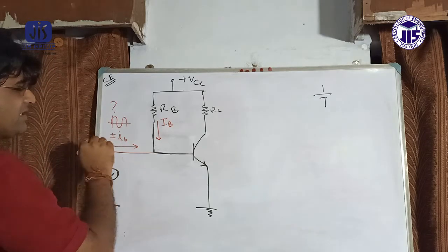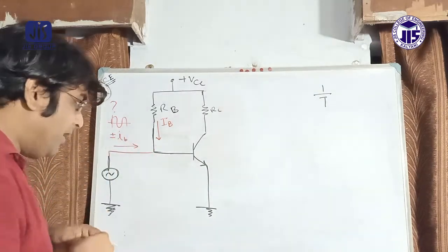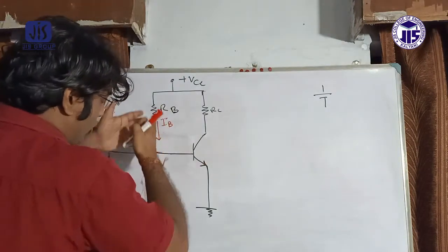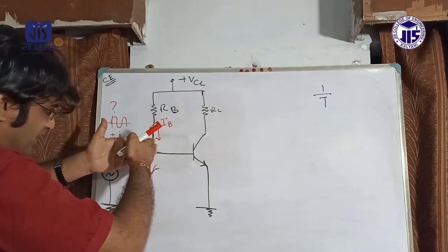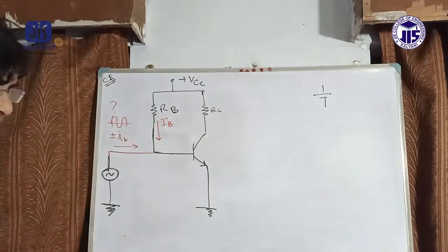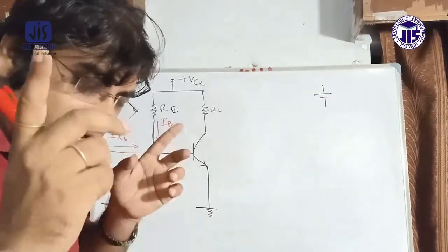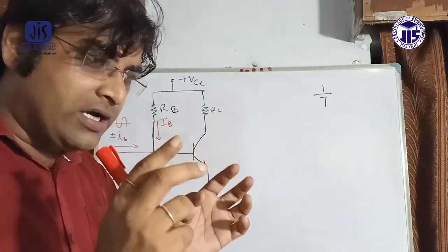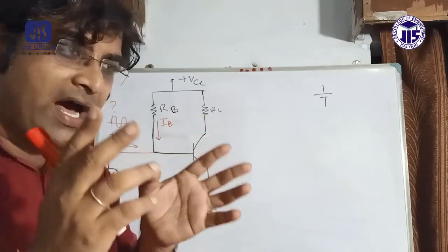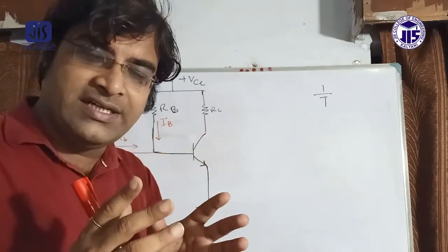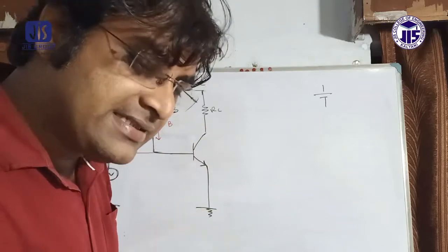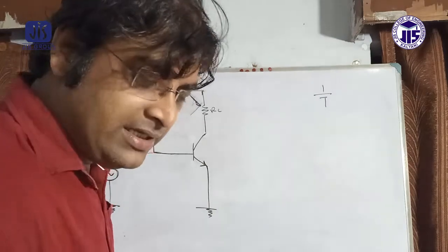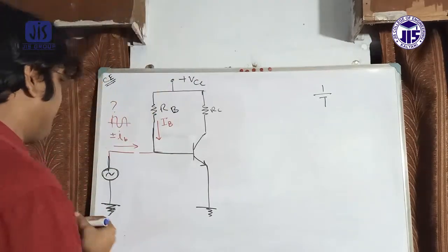I do not want to bring in the huge complexity of the circuitry, but to understand this I am just representing this simple circuit with an AC signal source, because the capacitor passes AC, so DC is blocked. DC comes in this side, plus minus ib like that. If I change the base current, IC changes, and the change of IC can be detected and collected from here. So this is the AC output VC on the output side, when IC is hugely changing.